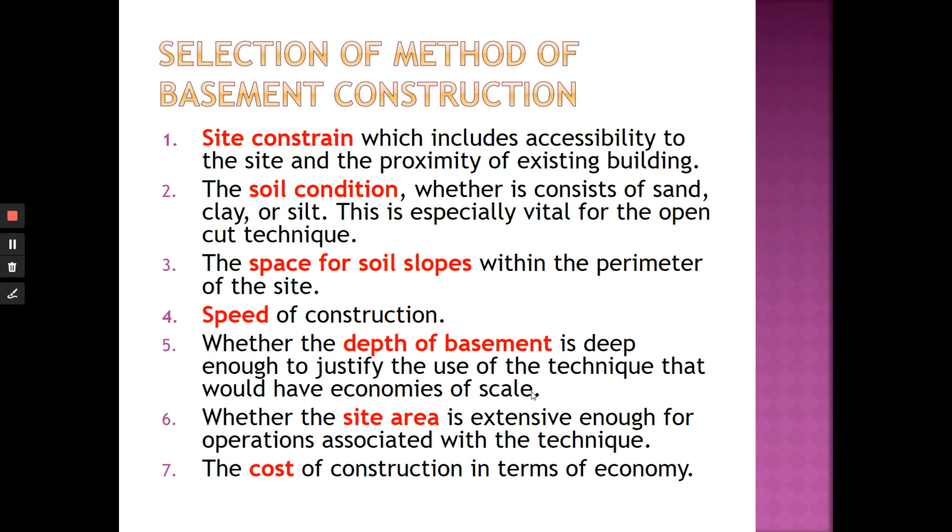Let's say your basement is just one level, and you want to do cut and cover. You need loads of time, and you probably waste a lot of money because you only have one level. So it's best for you to just use open cut. But it depends. You can also use cut and cover. Maybe you use soldier piles. But normally if one level, they will just use open cut.